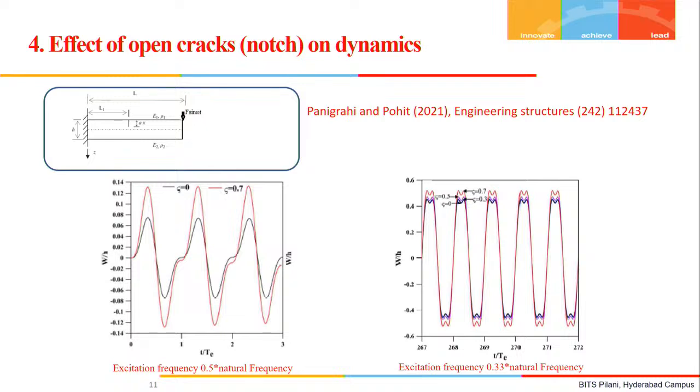Now, if we talk about some nonlinear attributes, when we model it nonlinearly, because nonlinearity is inherent, we cannot avoid it. We are now talking about the effect of the cracks on the nonlinear vibration behavior, and that too when we are exciting that particular beam, which has one crack, with some harmonic excitation f sin omega t.